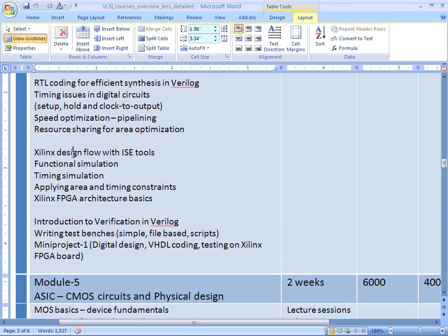It will show that between this clock and this clock you have maximum latency because of maximum delay, because of which your maximum clock frequency is only 100 MHz. Then we will apply the techniques that we learned to improve the speed. And second, let's say we take a bigger design that has 10-15 paths. Out of those paths, one path is really the critical path for you, and the remaining paths, even though they look like paths, the data is not changing in them. So they are called false paths. So we will learn how to give the information to the tool that you optimize this path only and ignore these paths. All this we will learn in the Xilinx tool.